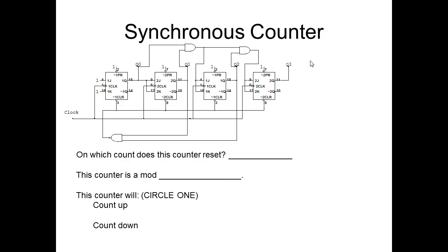The reason why you'd want to use these is that they're going to change every time. In other words, every one of them is either going to toggle or not toggle at the exact same negative edge of the clock. Whereas with the asynchronous ones, if you get a clock pulse that looks like this, and let's say they're all negative edges here, well, remember, we have a propagation delay, and propagation delay is actually going to push in a little delay between there and there.